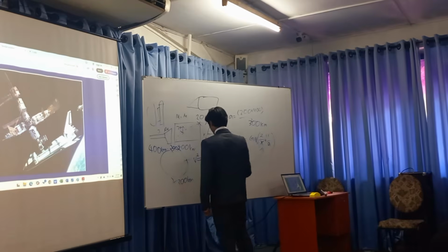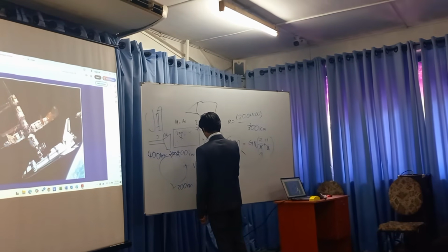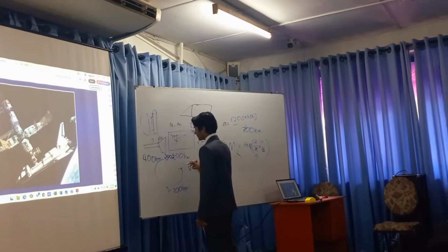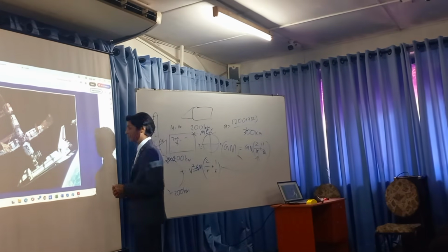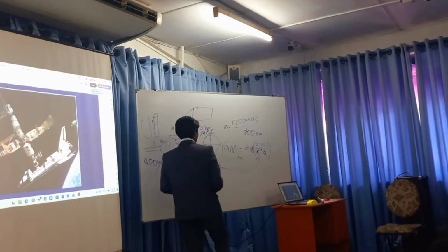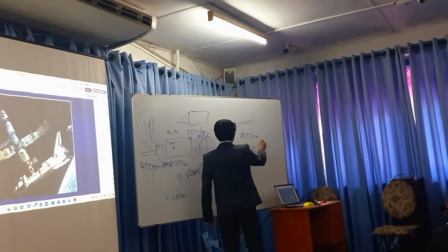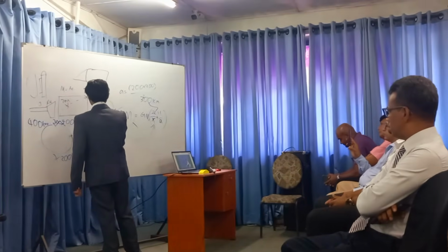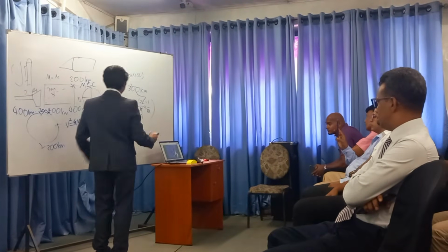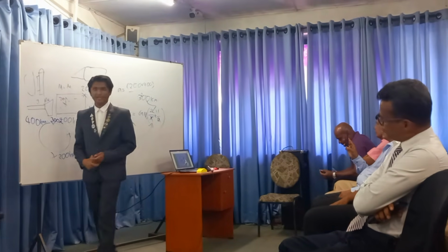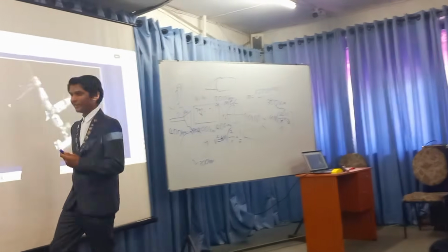This is the same system I mentioned before. Now, this is especially relevant for the second transfer because it means that once we have completed the first burn, which is the first part of the Hohmann transfer, we can say that this is burn number one. Let's pretend that this was 300 kilometers, and this, for example, is 400 kilometers. Our apoapsis after this burn, because our velocity is increased, will now be something like 400, 390, 380 kilometers.